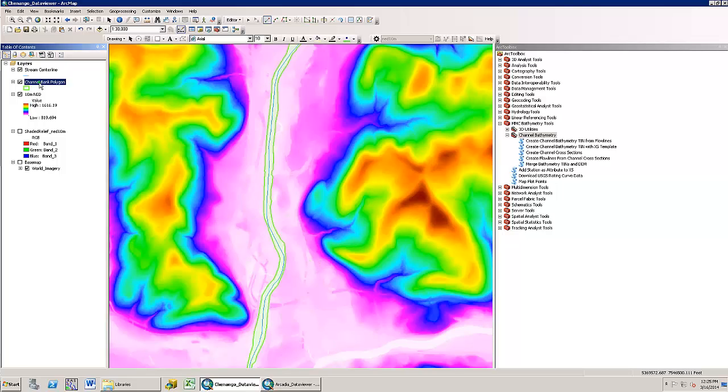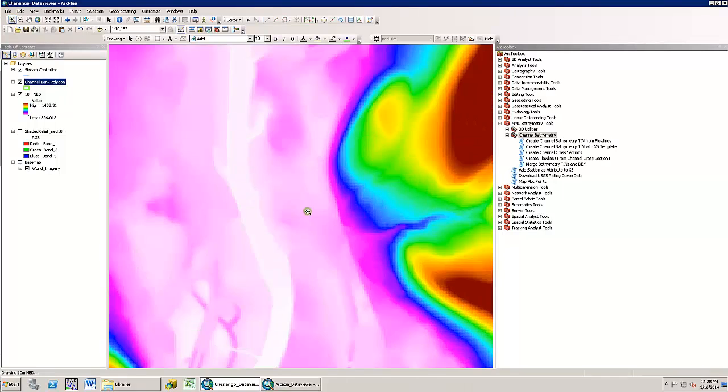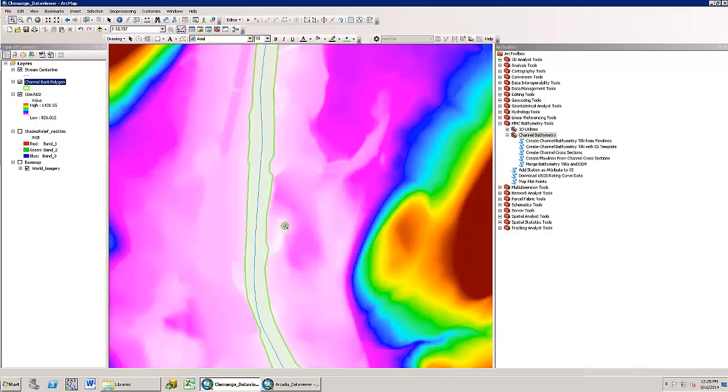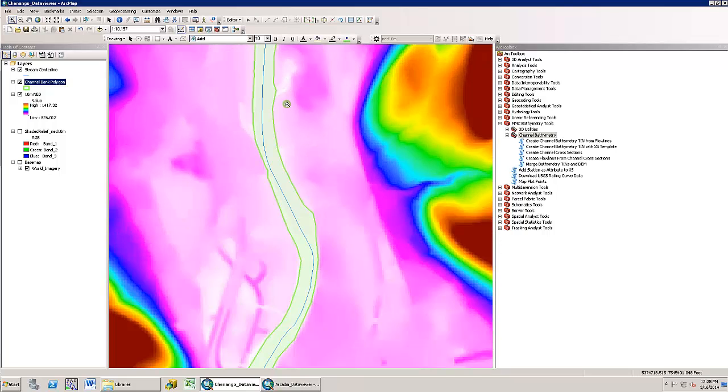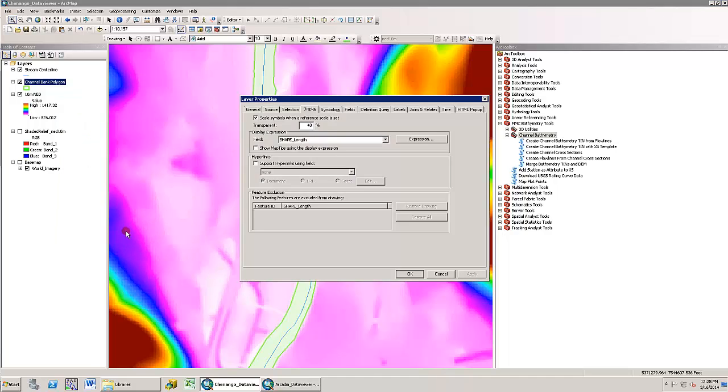I also have a channel polygon created. The polygon should represent the main stream channel and should not include large islands. For best results, the extent of the polygon should agree with the underlying terrain data and represent the channel bank elevations. For both of the input layers, they must have the same coordinate system defined with units in US feet.